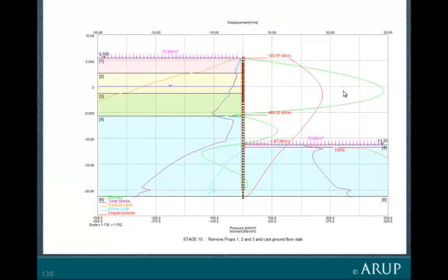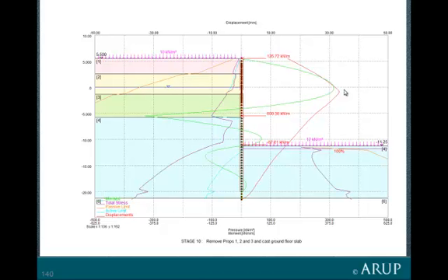With the rules in EC7, EC3 Part 5, it might be possible to do that by plastic design, if we allow a plastic hinge to form. So here's an analysis in which a plastic hinge has been able to form simply by making a section relatively soft, a short length of the wall, able to deflect more readily. You're required then to calculate how much rotation occurs at the hinge. Although it looks horrific here on this exaggerated scale, it's actually quite small, and it's well within the limits of EC3 Part 5. And you see what's happened to the bending moment.